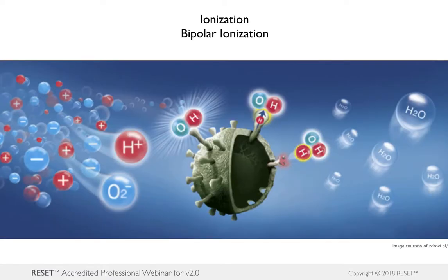But you can do it mechanically as well. And again, I'm using air quotes around mechanically because bipolar ionization systems create these charged air molecules by either adding or removing an electron using one of three different types of ionization systems, which is either photon ionization, nuclear ionization, or electronic ionization. And one of the benefits of bipolar ionization is that the ions, conceptually and in most cases that we've seen with the systems that we've been looking at, seek out the oppositely charged particles.